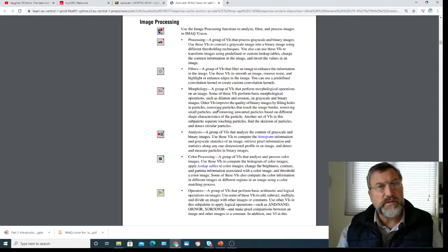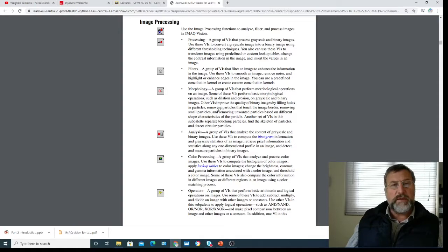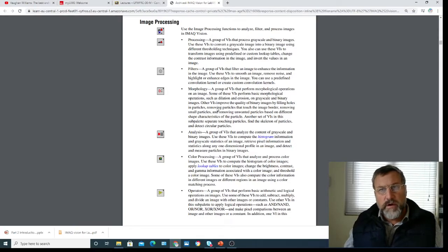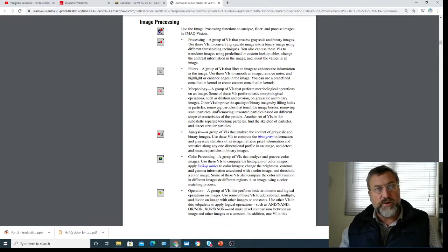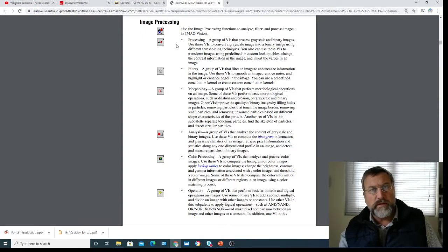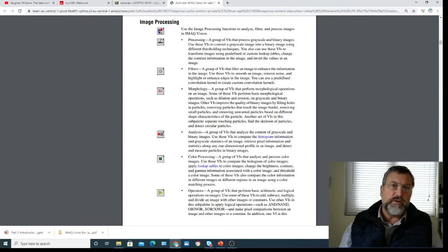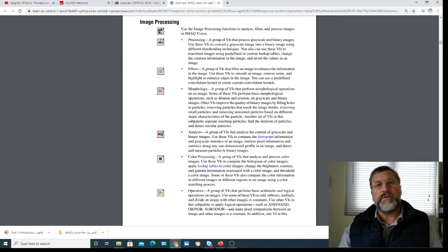I remember we were developing a system for a company in Salt Lake City some years ago. We had spent ages on it and got it working pretty well. And then the sun came out in the spring and started shining through the roof onto the thing we were trying to measure, certain types of boxes for air freight, using laser triangulation. And suddenly it didn't work, so it went into a spin, and we thought, how can we deal with all these changes in background light? One way of dealing with that in LabVIEW is special types of thresholds that will change depending on various parameters. But I'll tell you a good way of dealing with it is to do image subtraction.